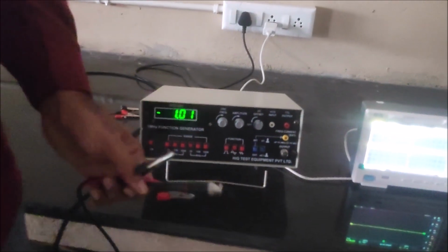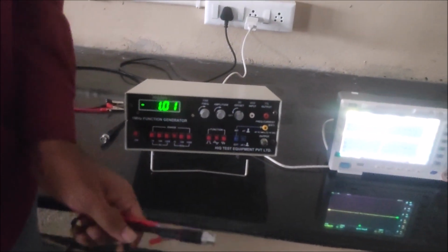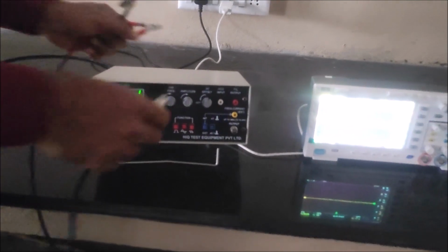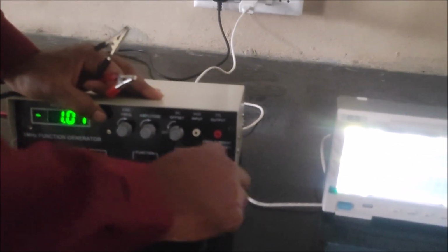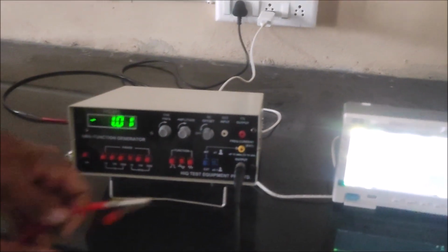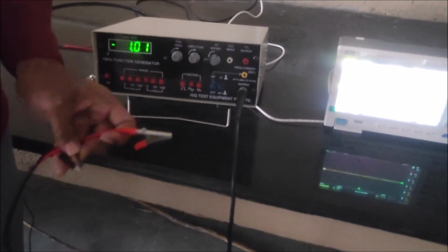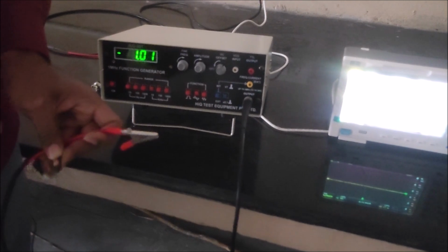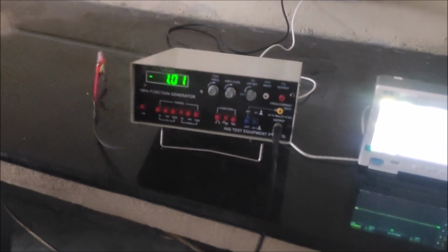But as we discussed already, if the signal is given directly through a wire, it might be attenuated. So I am connecting by using the same CRO probe, with the BNC connector. Here the signal is there now, but we cannot observe it with our physical eyes. In order to see the signal, we have to connect this signal to the CRO. Now I am taking one more BNC connector and a CRO probe.